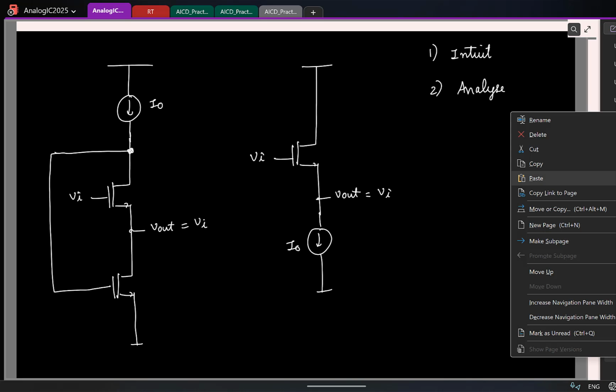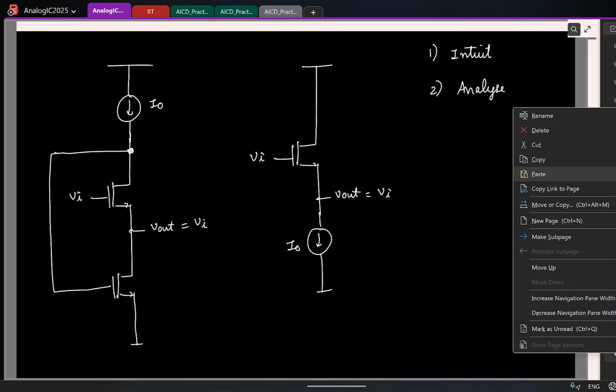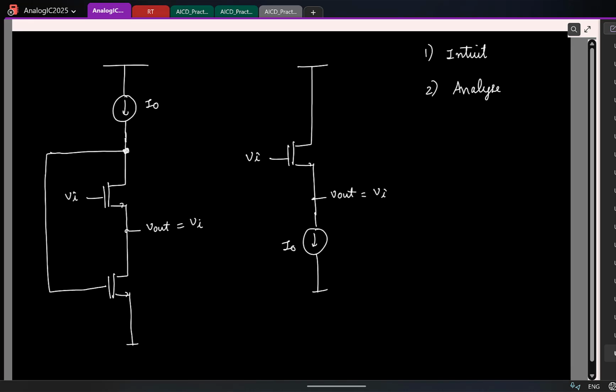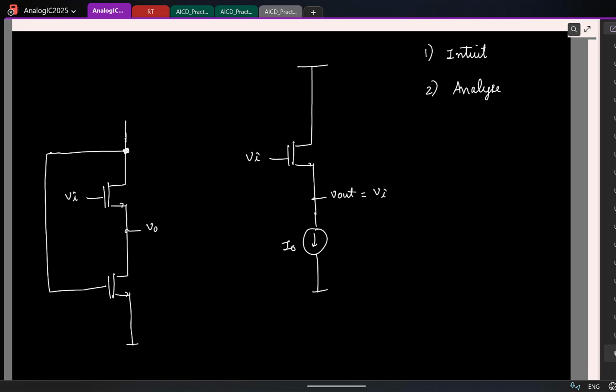And again, let's do small signal calculations. So help me because I don't exactly remember all the results. So for small signals, I'll open the current source. So let's try to find the short circuit gm and RO. That is easier. So I'll find the short circuit gm. I'll short the output here, and I'm trying to find the current here.